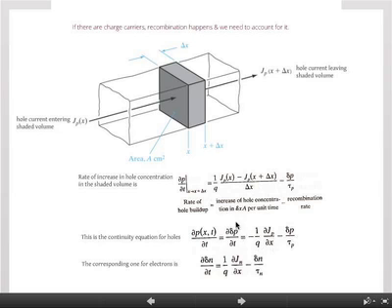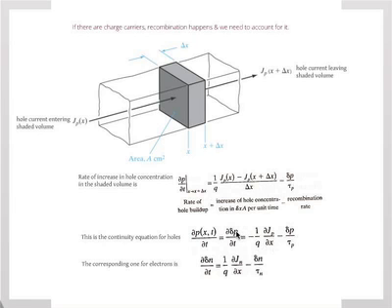Okay. Now, of course, this small delta p is defined as follows. So the total concentration of holes, which is now a function of space and time, is given by the initial concentration, which can be a function of space, but not of time, plus delta p. This is the excess holes that are generated. Of course, for most cases, we will ignore this, as in this example, because it's a uniformly doped semiconductor. So the total concentration is just that. This is a constant, so the derivative just becomes of that.